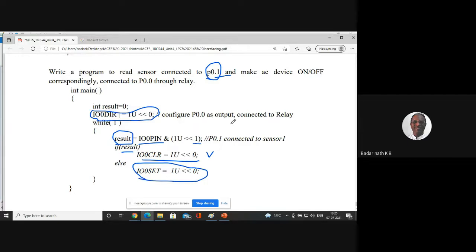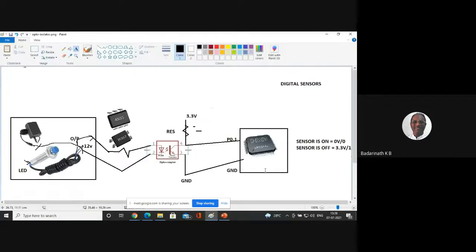We have connected the proximity sensor with the nuts provided onto the door. You can easily fix it. On one side of the door where the sensor is placed, you just paste a small metal piece, so that whenever the door is closed, only a 2 to 3 mm gap will be there. So automatically it will get activated. The only thing you have to do is purchase an adapter, fix it somewhere into the power plug and connect the power supply. And the relay you just introduce into the light circuit. Then a smart door circuit has been implemented. So this is how you can implement a smart door using opto isolators and relay devices. And you can build lots of projects using these concepts and this programming.